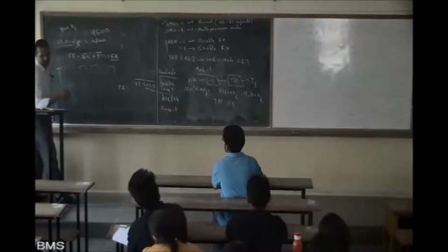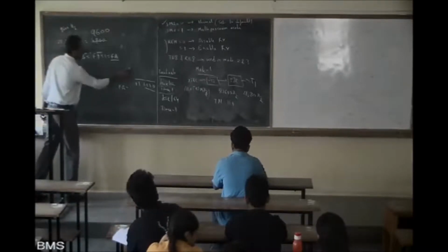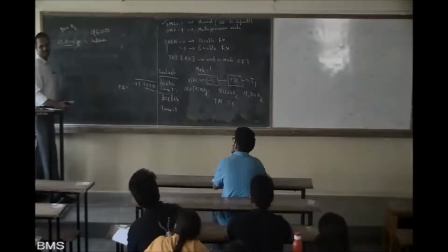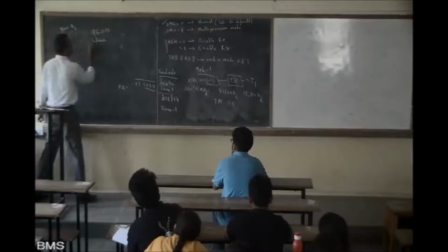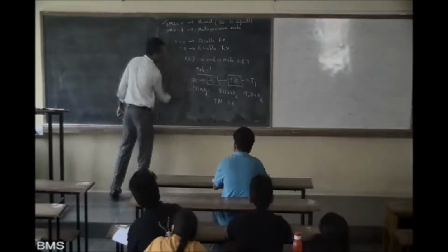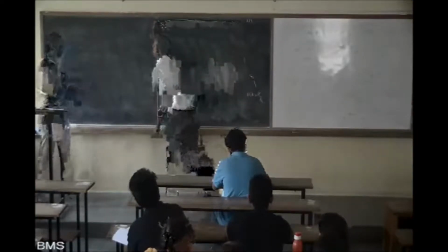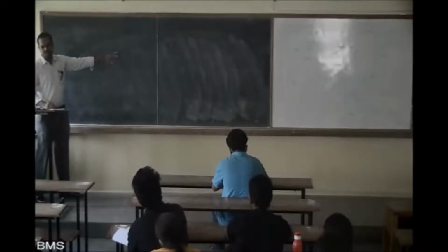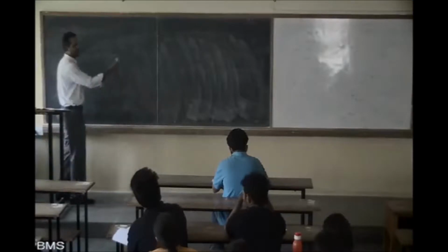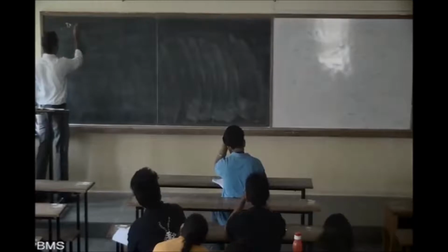Right. It is not there in the textbook. That is why I am stressing on this so much. You feel it is easy here. When you sit alone, you will get n number of doubts. This TF1 is by default connected to the SBUF. It will only send bit by bit. Okay. Right now, if I have to write a TX program,